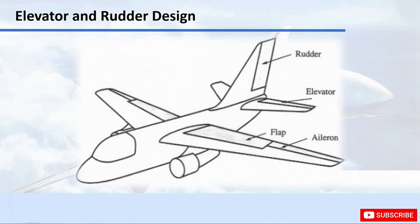And before starting, I just want to mention that these surfaces are called control surfaces because they basically control all the moments on the aircraft, which are the pitch, the roll, and the yaw moment, okay? And each of them is controlling a different moment, so basically they can move the aircraft in any direction in the 3D space. And today we're going to design them quite simply.